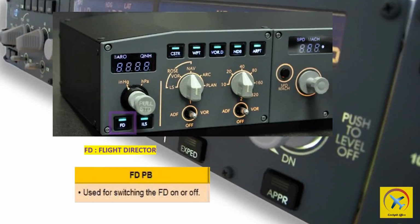2 FD2 annunciation indicates that both flight directors are selected on, but one FD has failed or one FMGC data is not valid. 1 FD2 annunciation indicates that both flight directors are on.